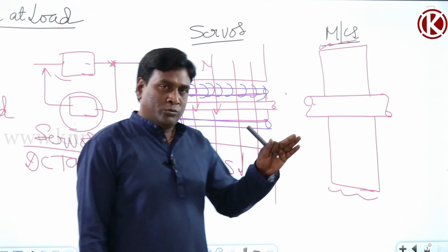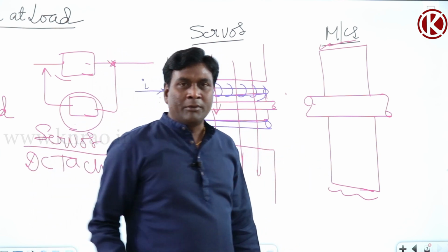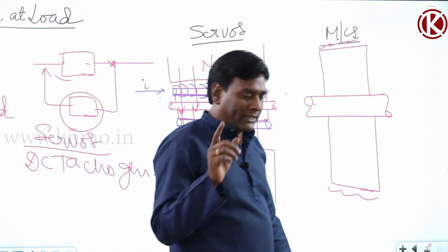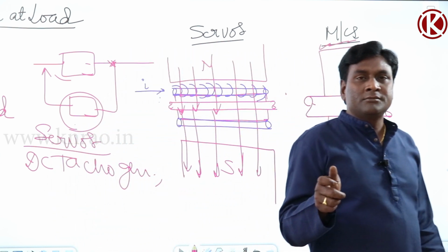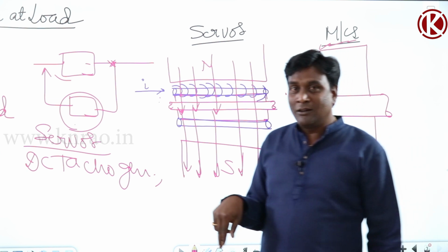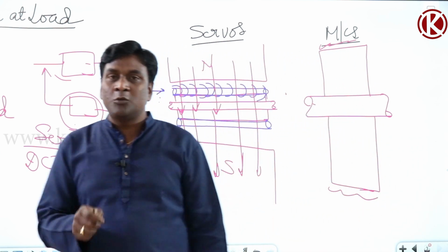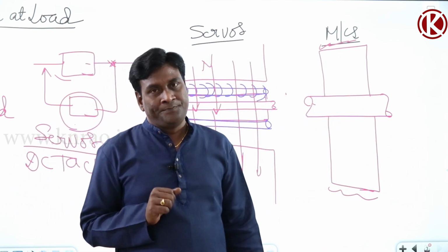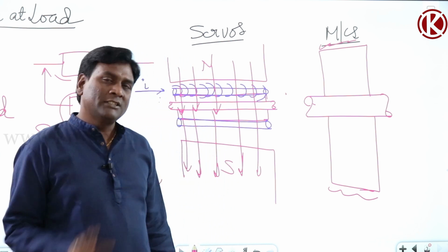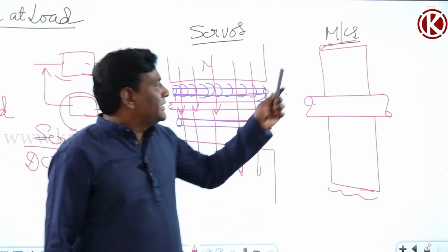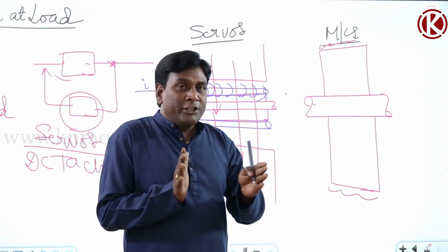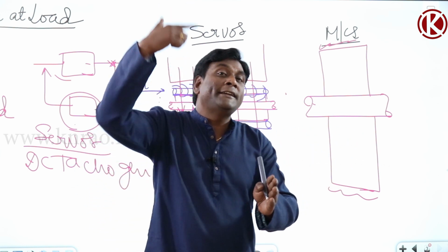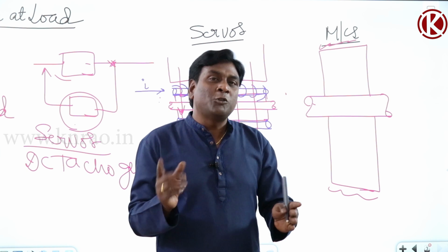So again coming back to here, previously I said one point, that we laminate the machine to reduce eddy current losses, and we laminate the servo to reduce time constant. How we will see in synchronous. Just keep that point in mind. Similarly, in machines, length of the shaft is reduced and diameter of the rotor is increased, to reduce cost of the machine.